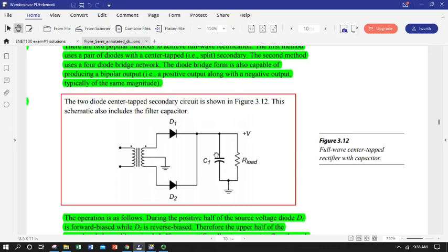And depending on how big our smoothing capacitor is in our load, we'll get a certain amount of smoothing. Okay, meanwhile, 1/2 period of time elapses, and now we've got our positive current flowing out of the other side of the transformer secondary. So now we're looking at our negative half cycle. That's the one we threw away with a half-wave rectifier.